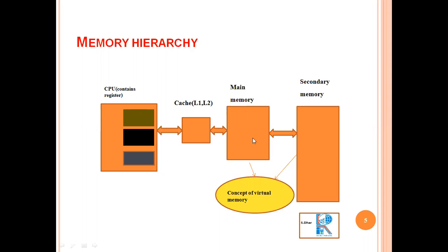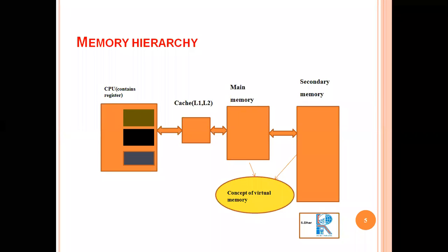How is it possible? Possible because here all the memory locations are accessed parallelly. At the same time, they are accessed and checked to find out whether the address is matched. If the address is matched, they will access the particular data. They don't have to go from the first to the last. So this is called random access, as opposed to sequential access. Obviously, the time required for random access will be minimum.